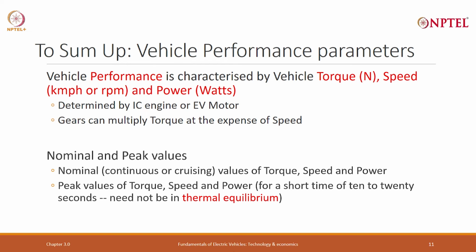Now, this is again something very interesting. I also did not understand it in the beginning. I have a 5 kilowatt motor, maximum power is 5 kilowatt. But a short period of time, the motor per se doesn't get limited by 5 kilowatt. It is a controller which gets limited. I can push the controller to give you 8 kilowatt power. But what will happen when I do the 8 kilowatt power?